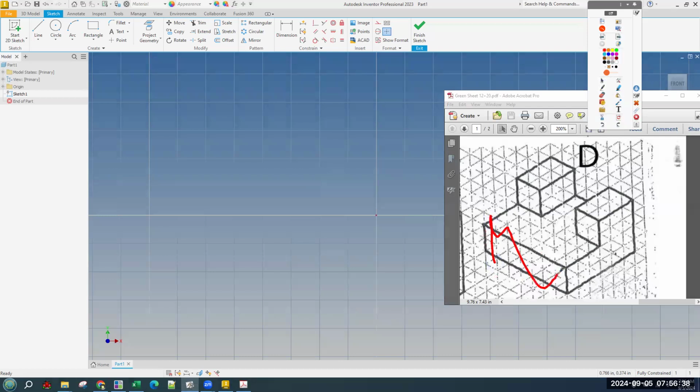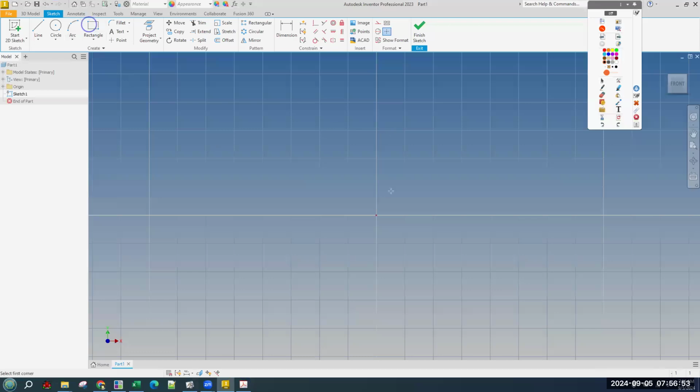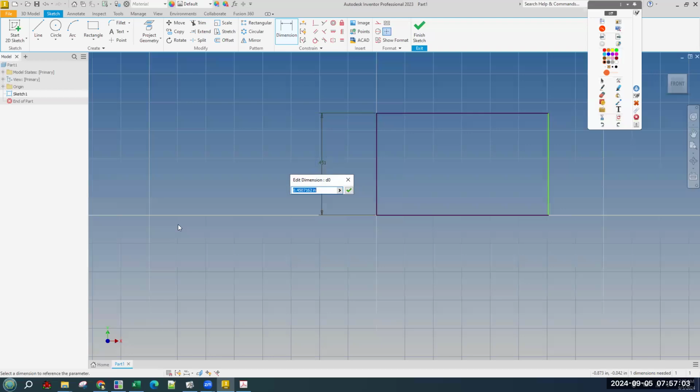Okay, so from where we are here, we are drawing on the front of everything. So let's make a rectangle that's 2 tall and 7 wide. And then we will extrude it 6 deep. 1, 2, 3, 4, 5, 6, 6 deep. So a rectangle, snap to 0, 0, just to anchor it somewhere. And dimension tool, and dimension the width first, or the height. First click there, second click there. And our height was 2.